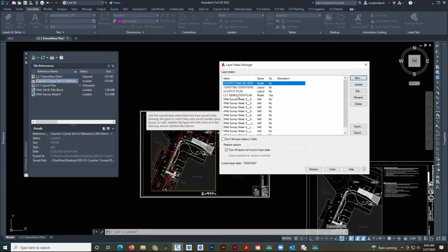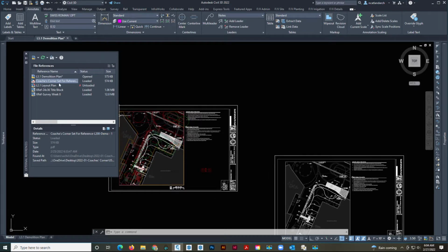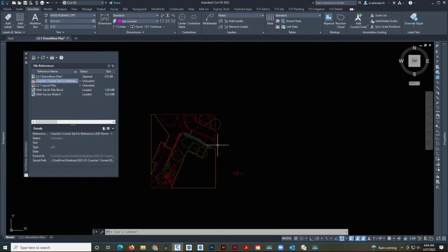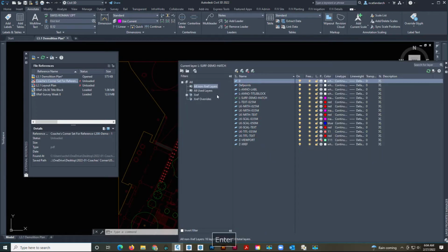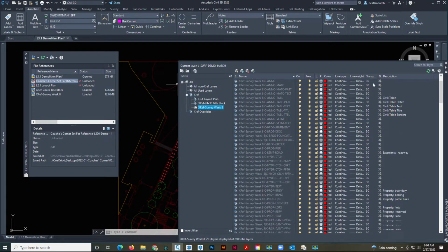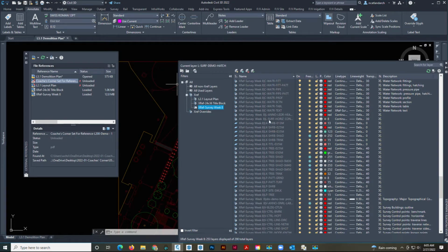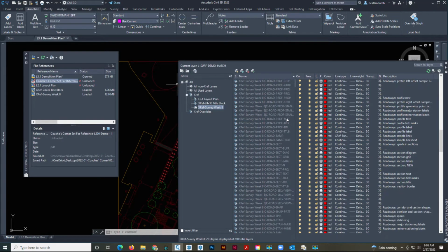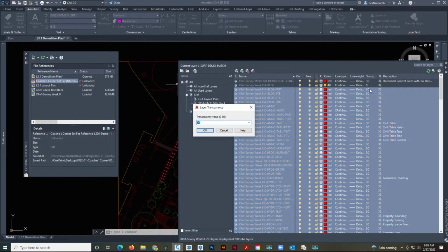That will allow you to go to demolition plan, which is cool, and I've already set some layer properties for you in that way, and then I'll just turn off this for a second because we don't need it. Okay. So what I've done for my layer properties in this instance, to save us some time, for my X references, and my X reference is going to be my survey, I've just set the transparency to 30%. For some of this, or for a lot of it. Well, actually, it looks like I set it to 40% and didn't change these. Let me change these. So I did this basically here. Let me make this 40.